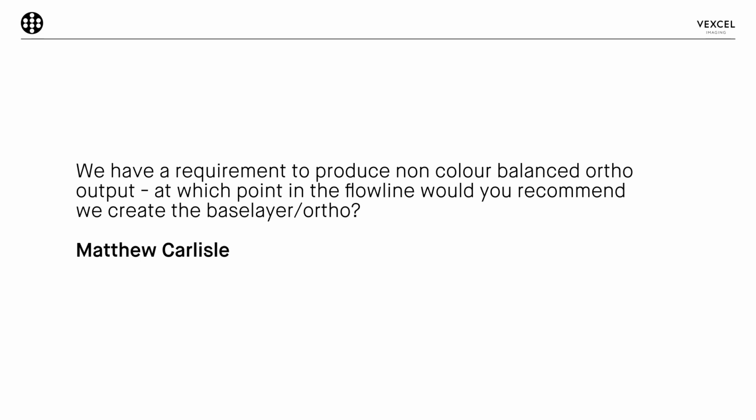Yes, so this use case is well supported by the new version of UltraMap. In that case, we would recommend that you first do the color balancing as if you would do just a production for one version of your data. Then you go for the DSM production, so DSM processing at high resolution. And that DSM is then the starting point where you go into the one direction with a color balanced orthophoto and into the other direction with a non-color balanced orthophoto.